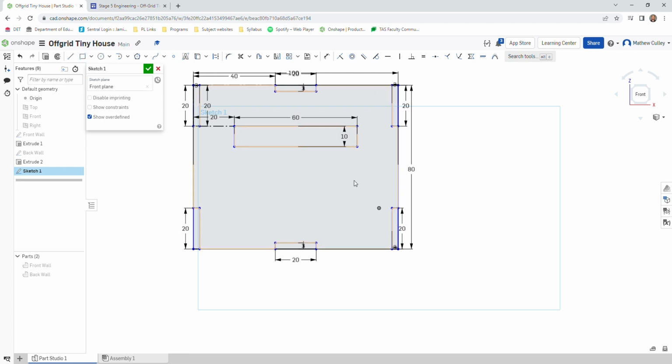Okay, now we're going to use our trim tool to start to remove some of this geometry in here so we can extrude this end wall piece. So M for trim, coming along, clicking on these lines here that we don't need. This bottom line here. Now we need to click that one twice because it has the construction line over the top and it has the previous.